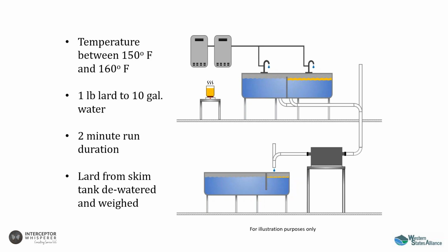So when it comes to the big debate about gravity interceptors and what's the most effective residence time, the fact of the matter is, with good flow and the correct environment, a 2-minute residence time is ample for performance. And then, of course, we're still using lard today. Some people have lots of questions about whether that's the correct media. I can explain to you later that it is certainly the correct media.